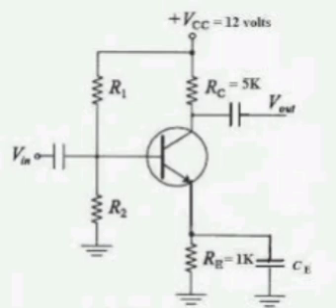5 ohms is in series with 5 ohms parallel with 20 ohms, in series with j3 ohms parallel with minus j6 ohms. Looking at terminals A and B, the Thevenin equivalent circuit is VAB equal to 20 into 20 by 25, that equals 16 volts. RTH equal to 5 into 20 by 25, that equals 4 ohms.